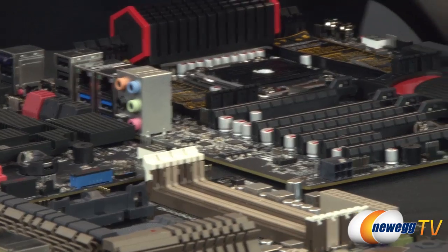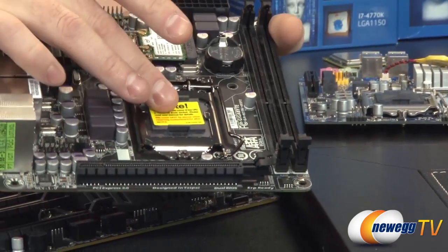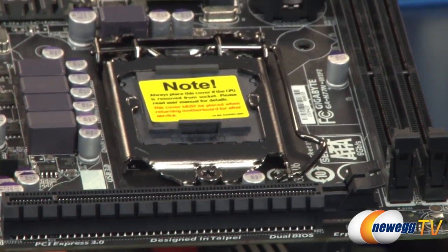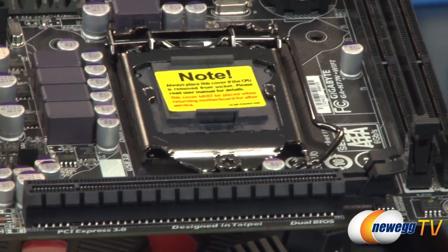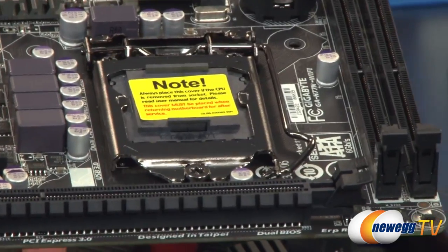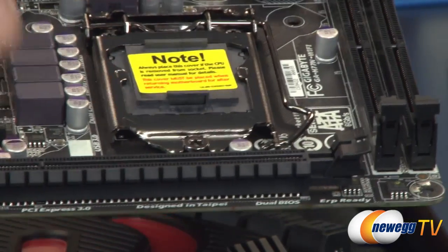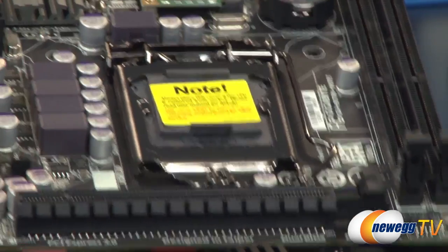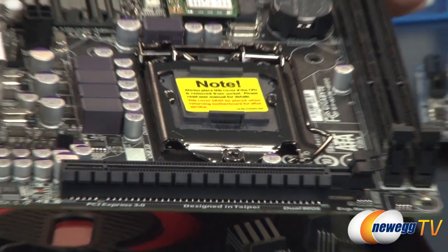Intel has gone with a lot of the same tech when it comes to their mainstream line of processors. So here again, this is a socket 1150 motherboard, but the actual layout of the socket and the spacing of these has been the same. Intel has maintained the same spacing going all the way back to socket 1156, which is a good 4 years old now. So 1156, socket 1155, and now socket 1150 all have that same layout, which means that you're going to have compatibility with your CPU coolers, even if you're carrying over an old one from an older system or something like that. But keeping your CPU cool is definitely important.